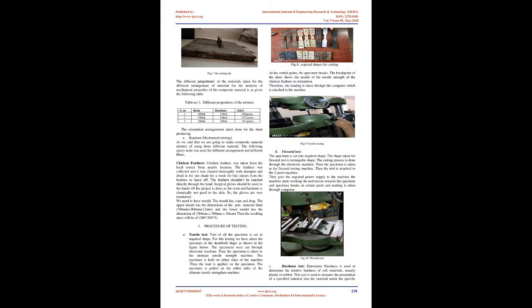In structural applications, the matrix is typically composed of a lighter metal like magnesium, titanium, or aluminium. In heat applications, cobalt and cobalt-nickel alloy matrices are common. Typical MMC manufacturing is essentially divided into three types: solid, liquid, and vapor.